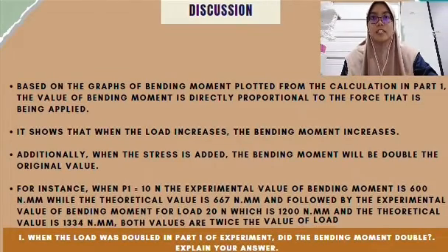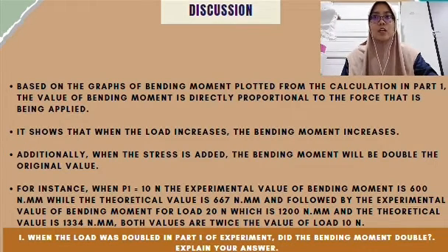Okay, continue with the discussion part. First, the question is, when the load was doubled in part 1 of the experiment, did the bending moment double? Based on the graph of bending moment plotted from the calculation in part 1, the value of bending moment is directly proportional to the force that is being applied. It shows that when the load increases, the bending moment also increases. Additionally, when the load is doubled, the bending moment will be double the original value.